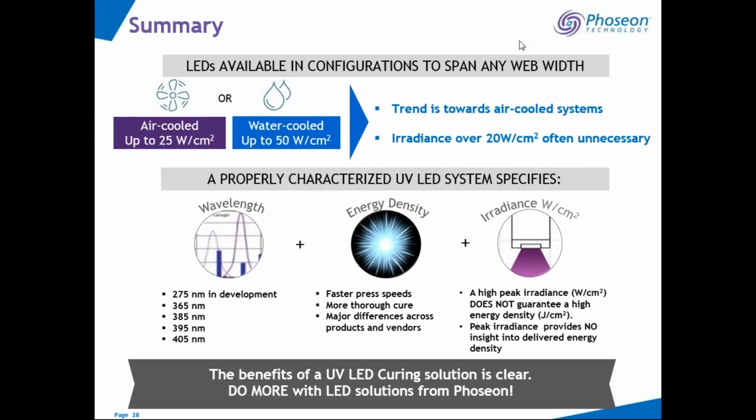The UV light that is output by an LED does not include IR, but it is a lot of intense energy. So as that gets absorbed and the curing reaction is kicked off, it does create a little bit of heat in that process. And if you were to stop the web in front of the UV LED light source, it will absorb that UV and turn into heat. So we do have to be a little bit cautious there. Just because it's the transformation of energy, it is turning into heat. So we have seen that IR can help the solution, but it's not necessary to reach our target curing speeds.